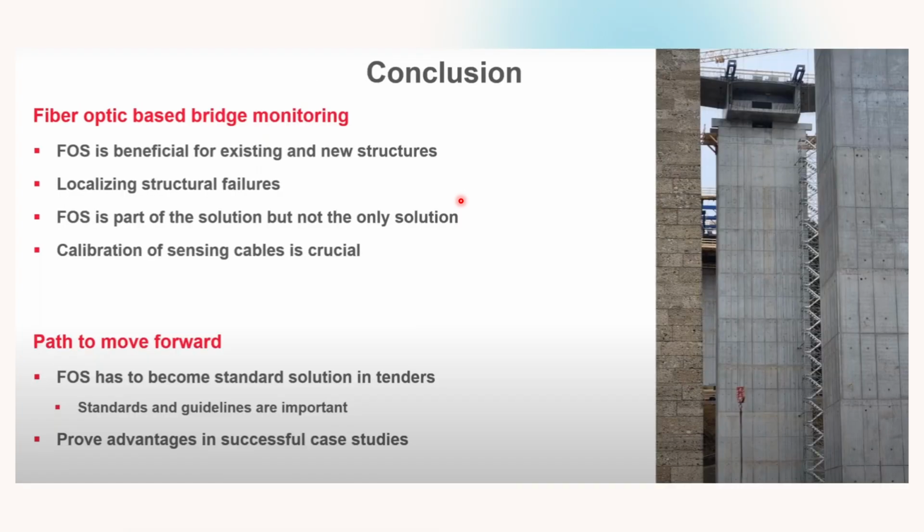The conclusion of the first topic is FOS is beneficial for existing and new structures, localizing structural failures, and also FOS is a part of the solution but not the only solution. Calibration of sensing cables is crucial in this environment.